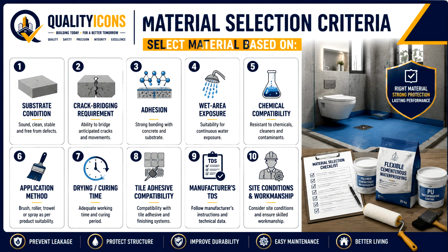Material selection criteria. Coming to this slide, before selecting a waterproofing material, the QA/QC team should evaluate several criteria. First, the substrate condition. The substrate must be sound, clean, and free from major defects. Second, the required crack bridging capability.